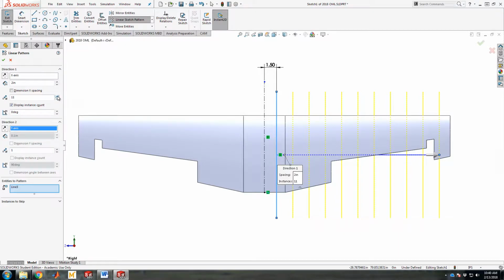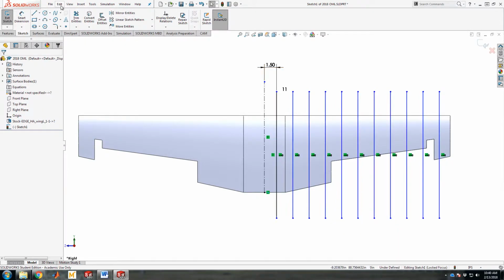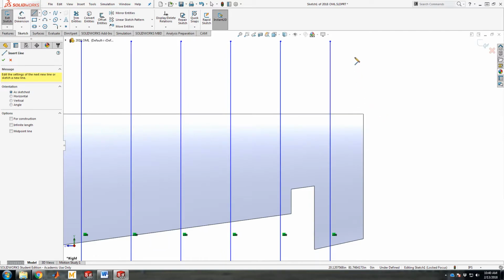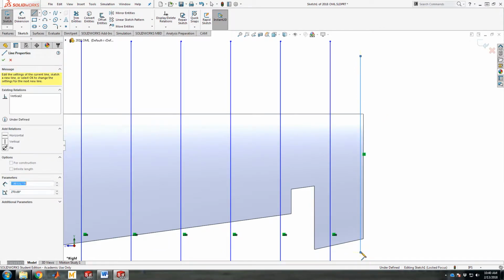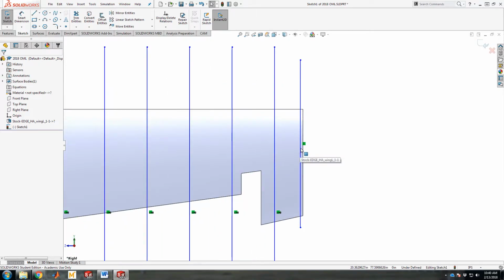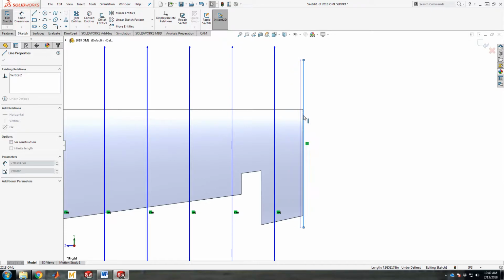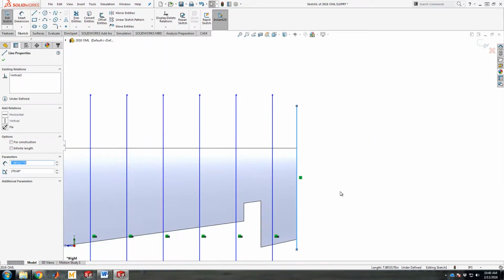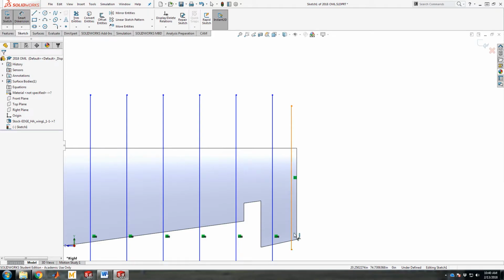The end spacing is not beautiful, but that's okay. We'll create those. And then I will manually come out here and create 1 rib close to the end. Now this is an interesting rib, because if you put the line straight on the end cap, and you thicken it, then part of the solid surface is going to be inside the body, so part of it's going to be out. So we know that we have 3/32 of an inch thick balsa, so I'm going to go ahead and dimension this as 3/32 of an inch away